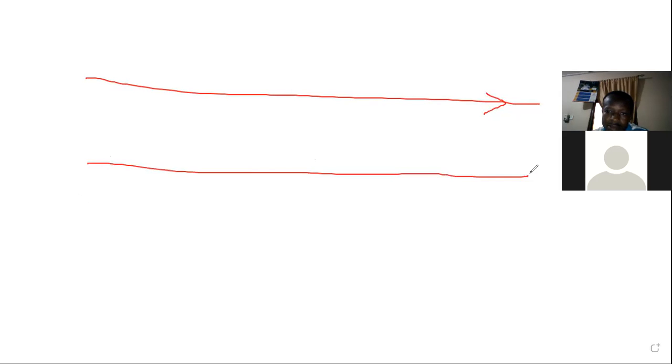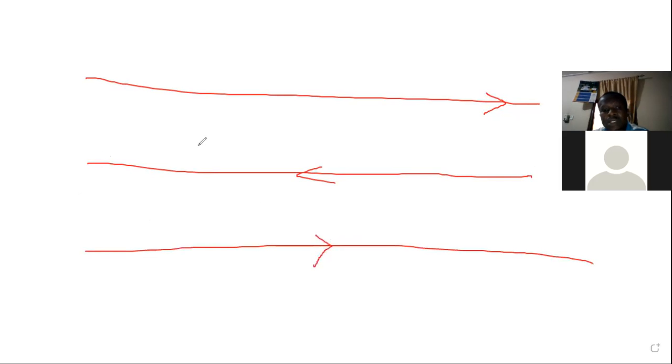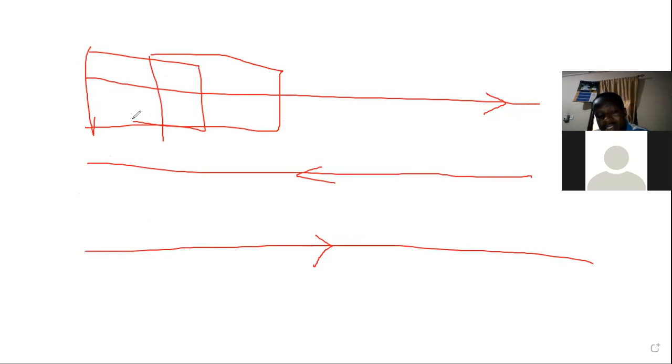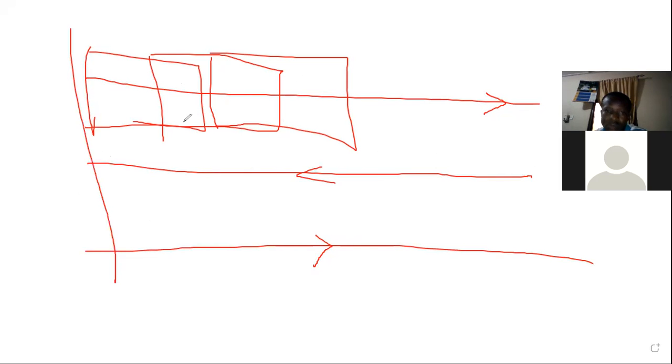So, what are we actually saying? Vertical photographs should be taken along parallel flight strips. So we fly one way, we come back, fly the other way, come back, fly the other way. As we go, we are taking pictures. These pictures are supposed to be vertical photographs that are taken along the flight axis. So we go ten, come back, ten, come back, and we cover the project area. Okay. All right.